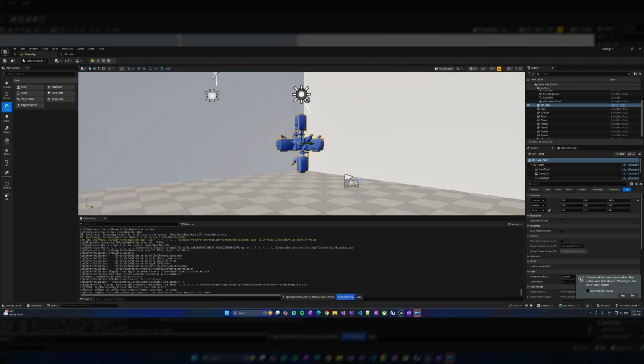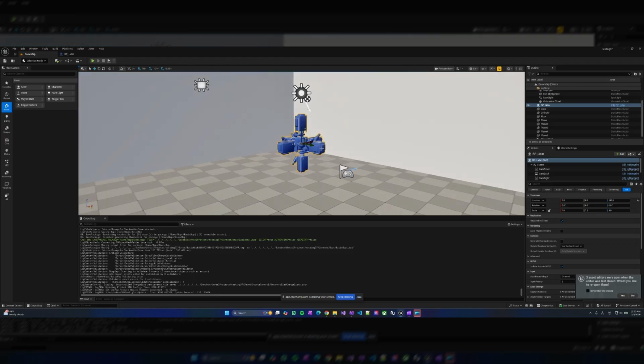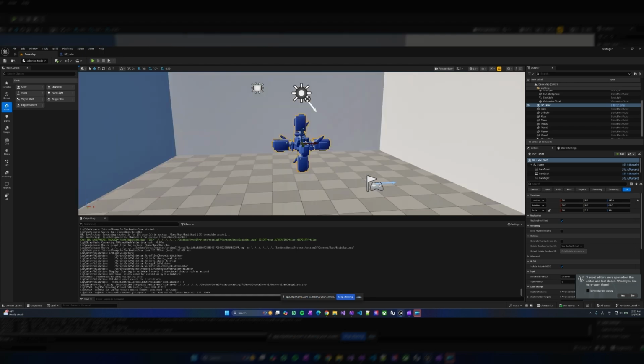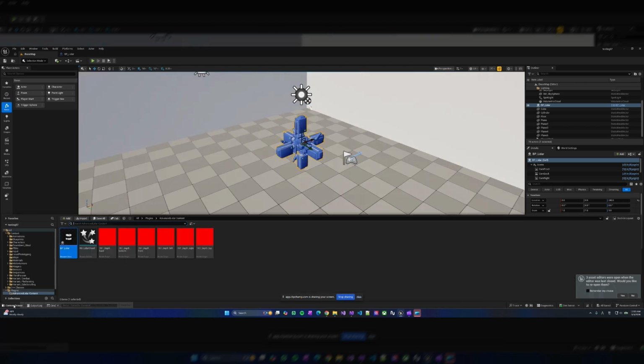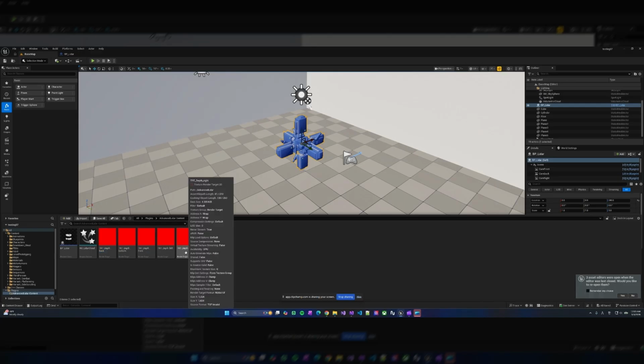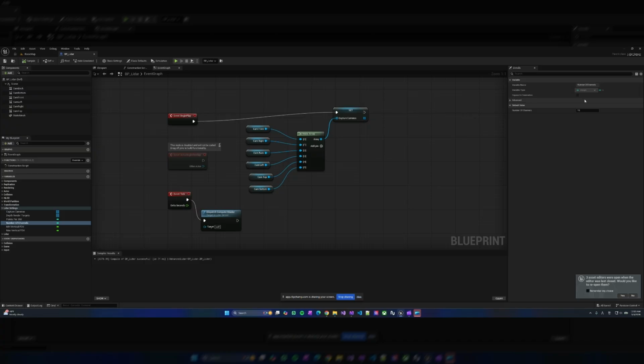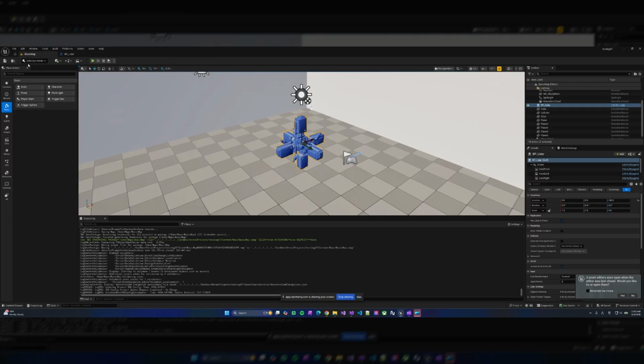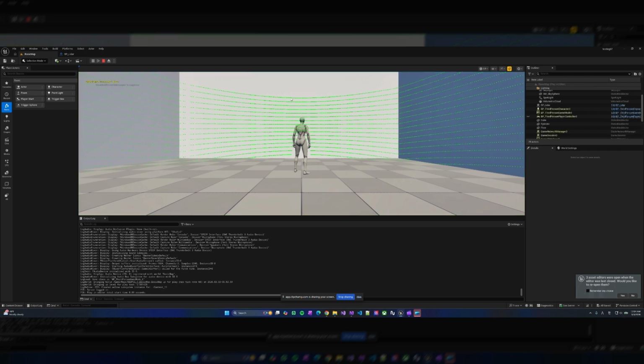As I've said, there are six cameras, with 90 degrees field of view for each one of them, and on each camera, I put six of these textures. Each texture captures the depth information in the red channel. That's why it's all red. Currently, I have the LiDAR at 16 channels, so 16 rings. And in each ring, I have about 1024 beams, and its field of view is -15 to +15. So if I start, you're going to see the green dots here.